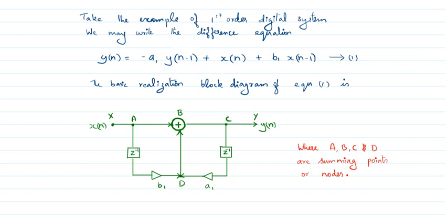So this one is the example for IIR filter. Okay. So in this I draw a block diagram of equation 1. So you can see x of n is given as the input, and next I give one delay, z raised to minus 1, with constant multiplier b1. So this portion satisfies this term b1 into x of n minus 1.